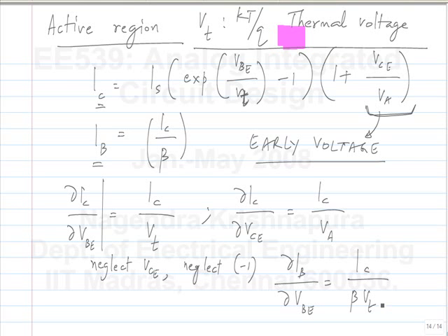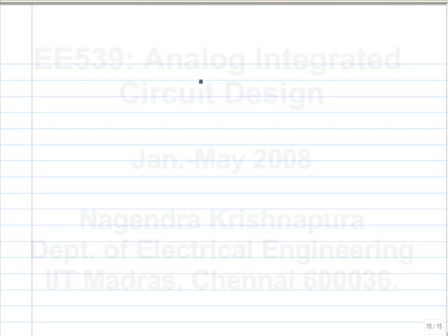And as I mentioned earlier, we won't spend too much time on this model. We'll just derive these expressions and go with it. The model turns out to be quite similar to that of the MOS transistor. Okay, in fact, it is somewhat simpler because we really have only 3 terminals. We don't have the bulk. We don't have an additional control for the collector current, okay. So just like before, we will have a transconductance that models the dependence of IC on VBE.